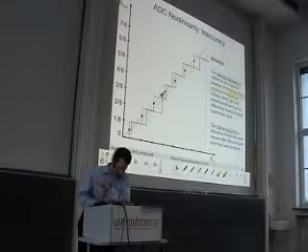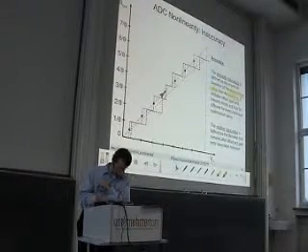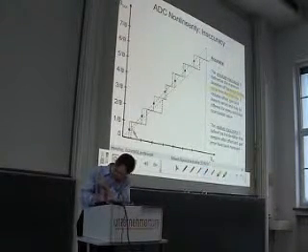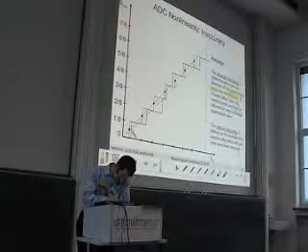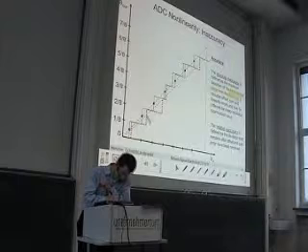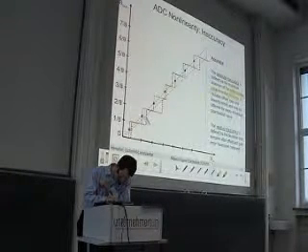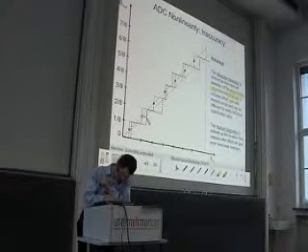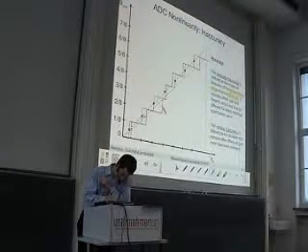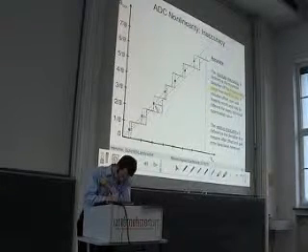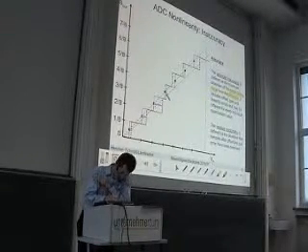So this is the midpoint of the steps, and the deviation of the actual point, which is here, from the ideal one is this difference. Here we can see it better. It is this difference. Actual analog value and ideal one. This is the actual one, this is the ideal one, and the deviation is the inaccuracy.